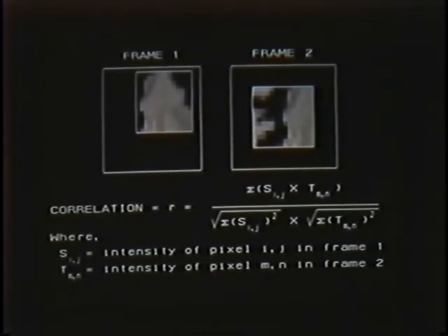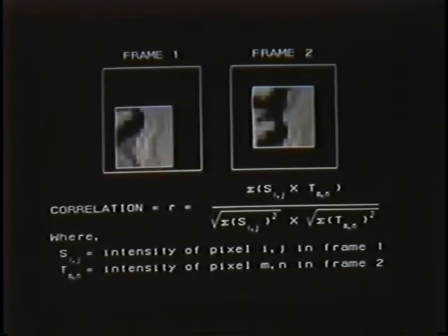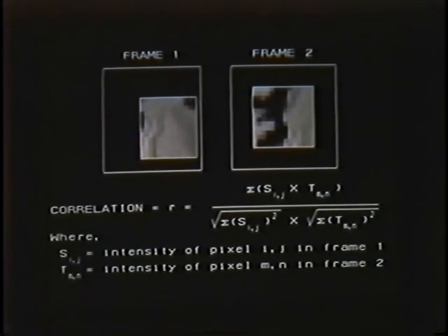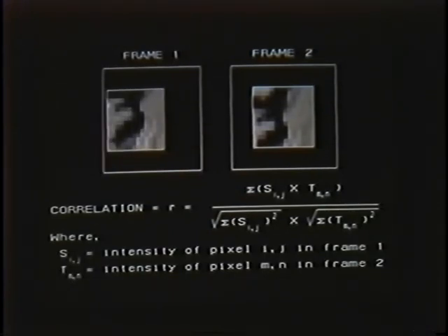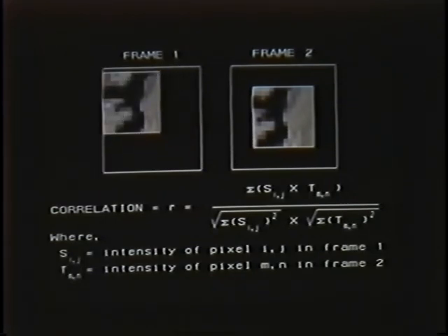We base the accuracy of our estimation on the observed correlation value of the pixels within the window, where a correlation of 1.0 indicates a perfect match and 0 indicates no match at all. Ideally, we want to achieve a correlation above 0.9.